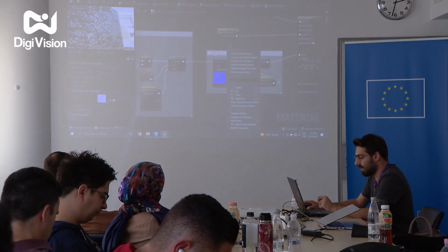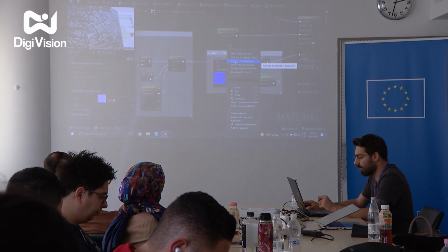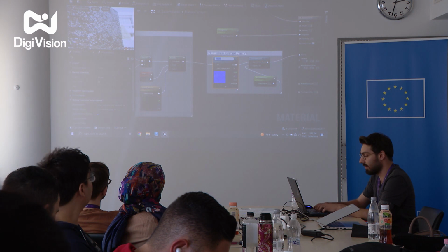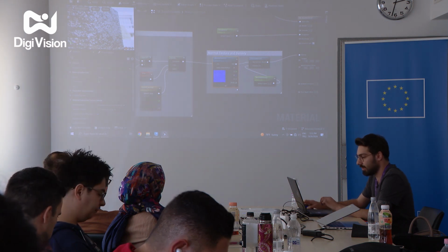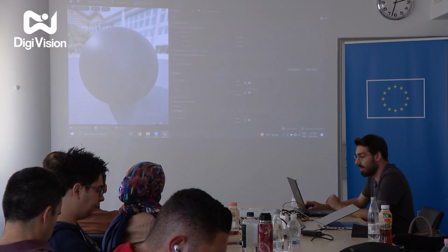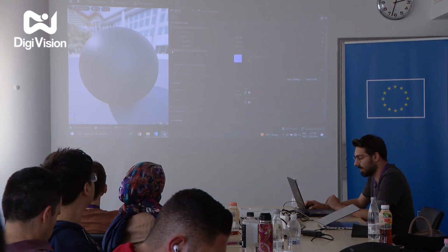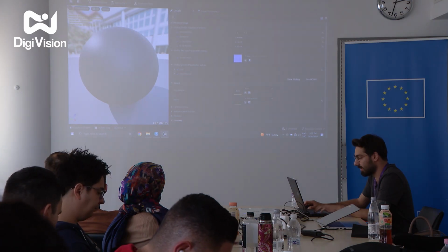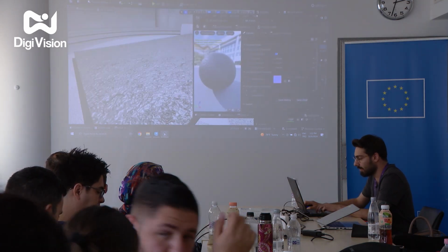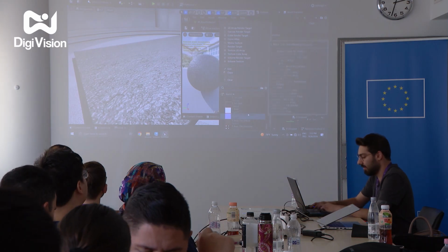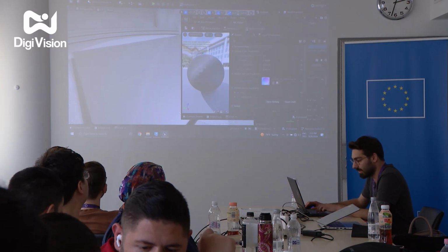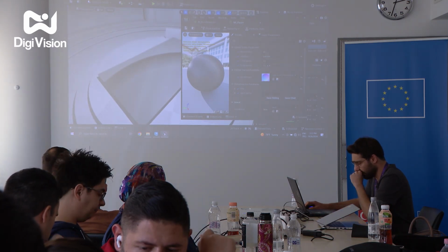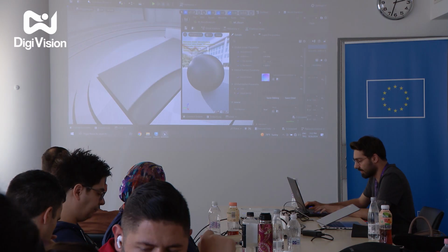So we can right click on the texture and convert to parameter, and we will just give a name for the instances, like normal texture. And when I apply, I will see the global texture parameter values here. So let's see our normal map, for example, in here, and we can select other normal maps, but we also need to make some adjustments for the scaling.